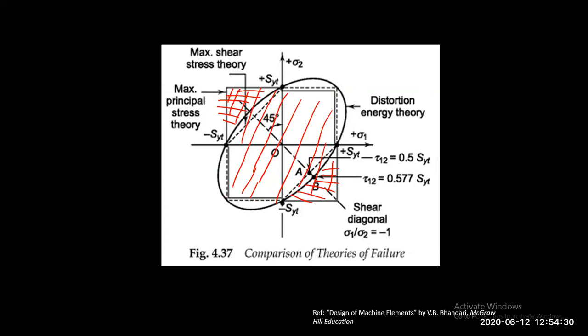So in this case, the maximum principal stress theory is a bit liberal, and this tends to add material. It is not used in optimum cases. Whenever you are designing components like machine beds, components which are really heavy, then you use the maximum principal stress. Like this, different theories of failure are used in different conditions. We'll see that in the next slide.